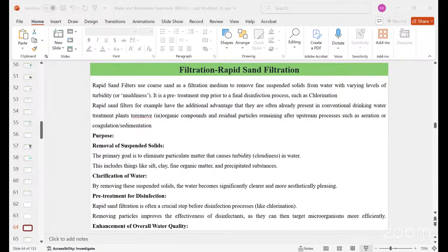And coming to the hydraulics of filtration, the flow of water, that is the dynamics of it, is called hydraulics. And understanding the hydraulics of the filtration is essential for designing and operating efficient rapid sand filters. It majorly involves analyzing the flow of water through the filter bed and the associated pressure changes. The first one is Darcy's law. So Darcy's law mainly describes the flow of fluid through the porous medium. It also states that the flow rate is proportional to the hydraulic gradient and the permeability of the medium in the context of rapid sand filters.